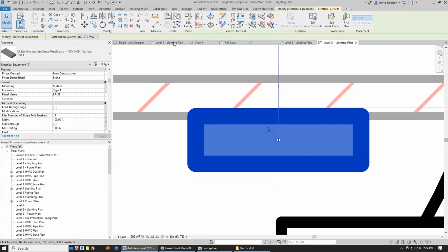Yes. You have to be aware of how the size of the transformer is being set, because Revit doesn't have a concept of a transformer size. They don't have a place that's an intrinsic Revit value to put the kVA. So our software and everyone else who creates a transformer family has to have their own special place to put a transformer size. So every single place you go has a different transformer size. So it's a bit of a coordination issue you have to be aware of.